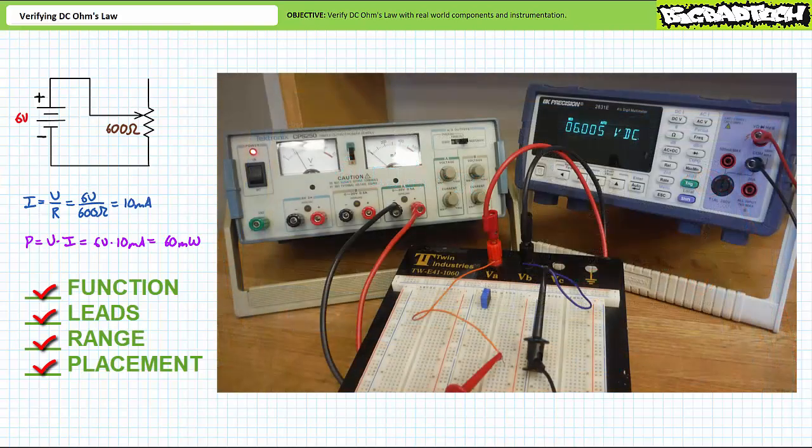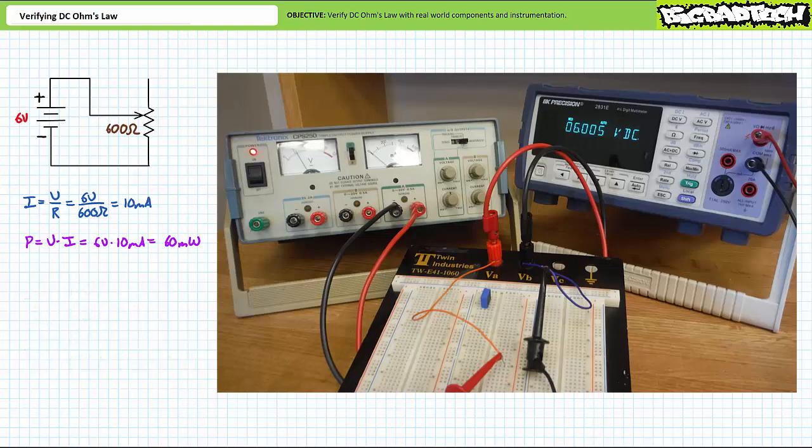Placement. Voltmeters measure the voltage across the two terminals of interest. Our terminals of interest are the positive and negative terminals of the adjustable power supply. When we turn on the DC power supply, the DC voltmeter demonstrates that with a couple turns of the voltage adjustment dial, we can dial it into the desired 6 volts. This is the unloaded voltage, meaning it is the voltage established by the supply when it is not providing current to a circuit.